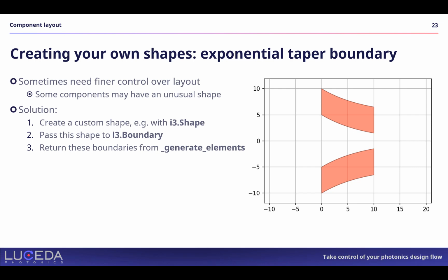There are situations in which you may need finer control in creating your layout. In this tutorial, we will go over some methods in which you can have this finer level of control. This is the case if you're working with an unusual shape. And the solution is to use i3.shape and i3.boundary.